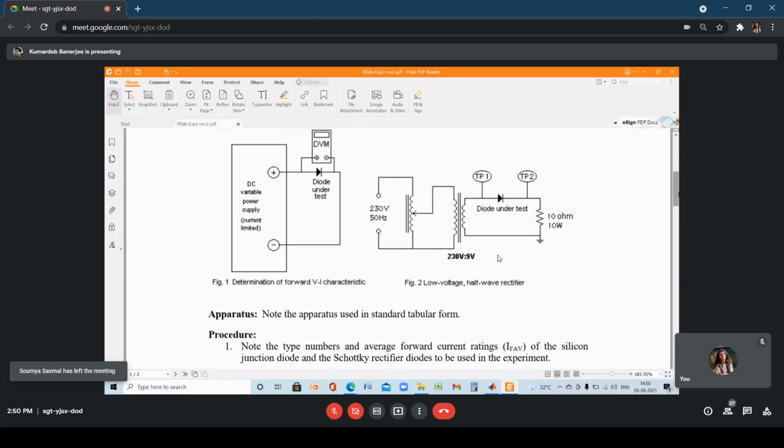But what is being done in this power supply is there is a control mechanism through which I can fix the current that can be drawn from the power supply, even in short circuit, to a predefined value. So there's a knob. Using the knob, you can set the current limit. So here we pick up one such power supply where this current limiting facility is inbuilt, right? Now this particular voltage is kept at 1.8 volt, right?